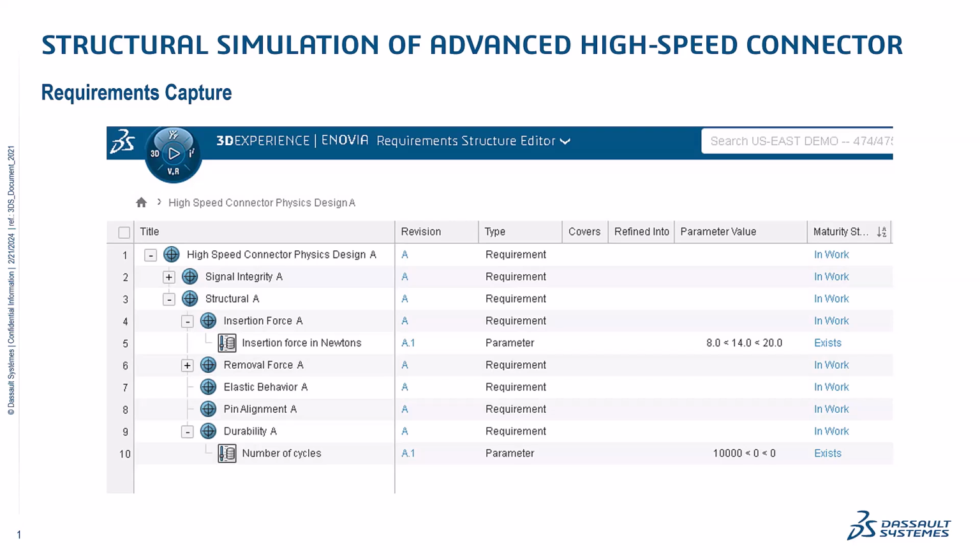Another design requirement is that there's no permanent deformation of the components during the insertion and removal process. Additionally, there are other requirements like the lateral force, the maximum lateral force before damage occurs to the connector, and another one, the mounting force to the PCB. So you can see there's an awful lot of structural requirements that need to be managed for this project, which increases the complexity, which is why this platform-based approach really does help to manage all of that complexity.